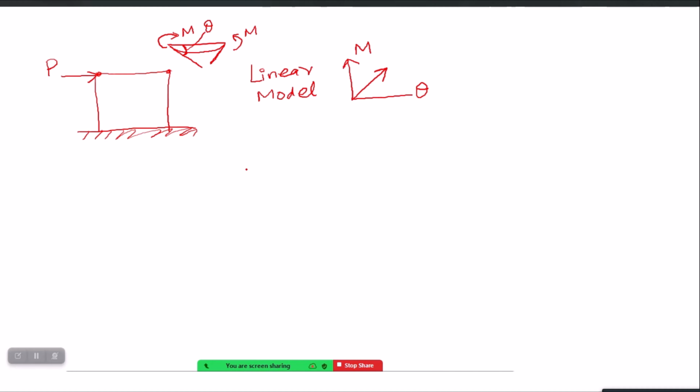This happens regardless of whether the bending moment produced by that unrealistically high P is something the beam will actually be able to develop, or whether it will fail or not. In a nonlinear model of the same beam, we will actually try to make this behavior as realistic as possible, or close to real behavior.